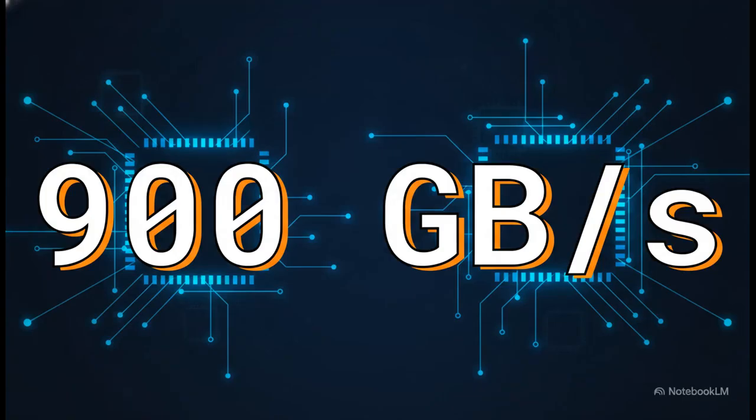Because let's face it, sometimes a single card just isn't enough. When a model is simply too massive to hold natively on one GPU, multiple GPUs have to communicate seamlessly with each other. This is where NVLink comes into play. It's Nvidia's high-speed interconnect technology, and it provides up to 900 gigabytes per second of bidirectional bandwidth between GPUs. To really wrap your head around that, that is roughly 14 times the bandwidth of a standard PCIe Gen 5 connection. There's literally no bottleneck there.